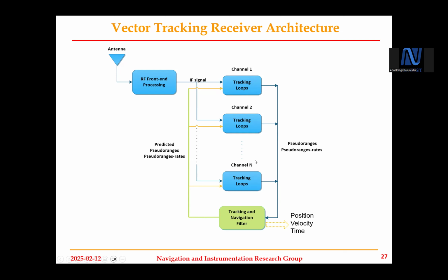Because we mentioned earlier, the position calculations are based on the pseudo ranges, right? And the pseudo range estimation is based on the delay. After I get my position calculated, for example, out of 9 satellites, I can tell this tracking channel my estimation of the range is this much, so I can tell them to derive the estimated delay, when I have information exchange between the other channels.